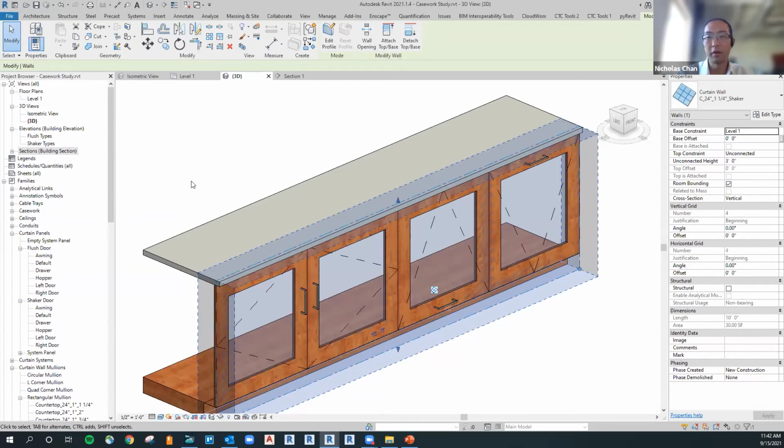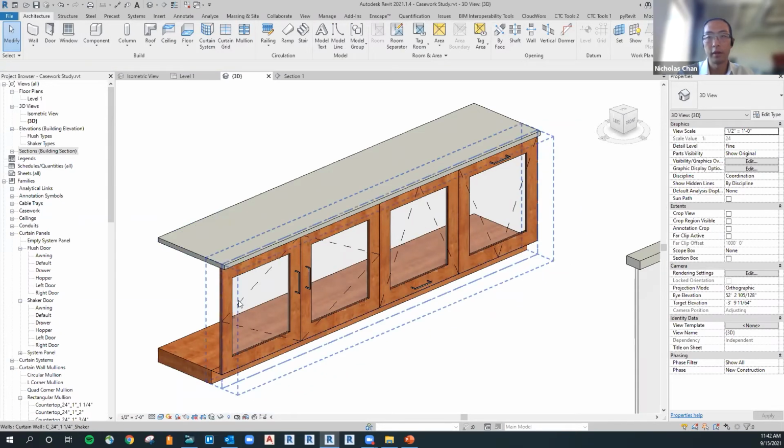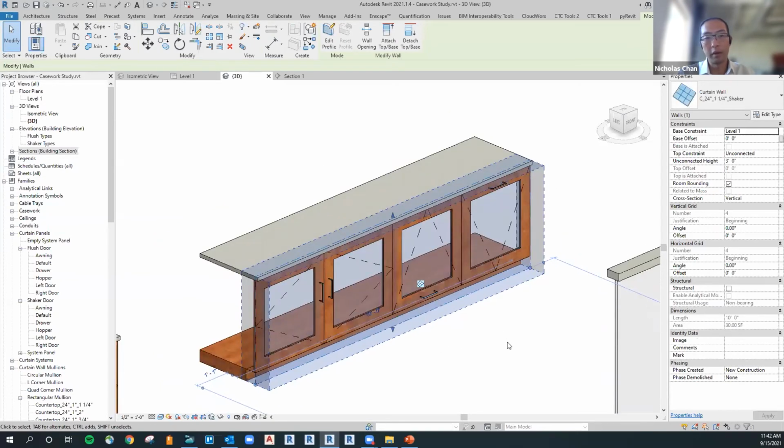There's another question here of how we deal with the categorical integrity of using walls for casework, and if there are any conflicts that we see coming about from that. This does relate in some ways to a backsplash. We would either model it in place or do a wall sweep for the backsplash to accommodate that.